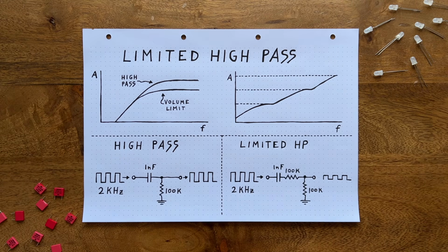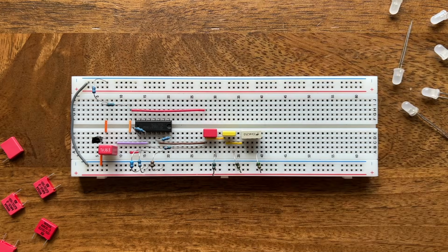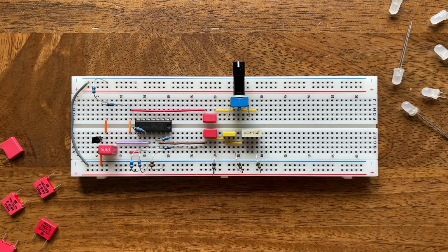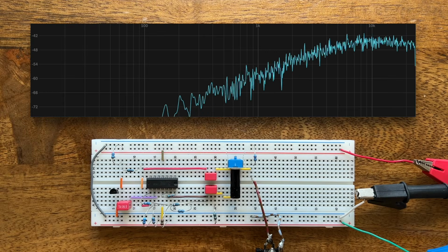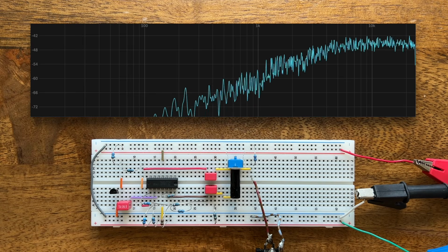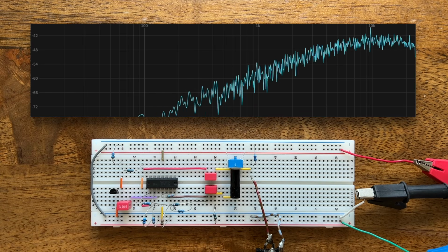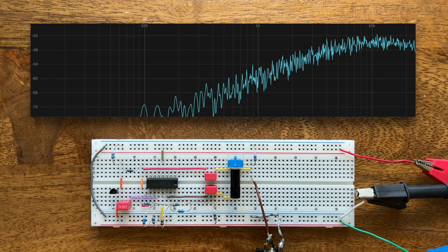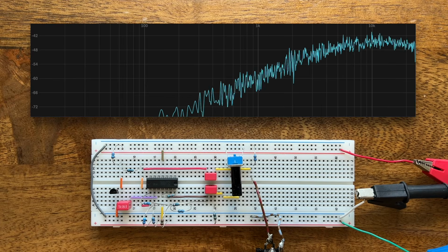To test this, I'll again replace the fixed resistance after the capacitor with a potentiometer. This way, we can dial in different upper volume thresholds on the fly. First up, I'll plug in the input capacitor. Then I'll route the other end through a 100K potentiometer. Slot in a 100K resistor to ground, and we're done. As an input signal, we're again using our white noise to properly visualize the circuit's effects over the entire frequency spectrum. Right now, I've got the potentiometer turned down completely. And here's what happens if I turn it up.